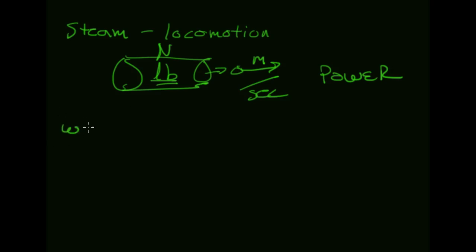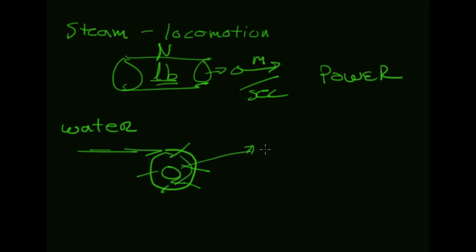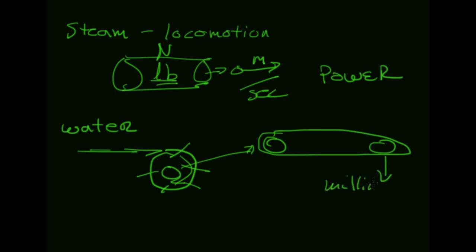We've seen historically that we've used water, and a lot of that is a matter of bringing water over a water wheel. This is like a precursor to the generator idea. So this turns the water wheel, and in turn, that turning mechanism could be geared, with belts and things like this, to turn other things. Using gearing, you can actually perform tasks like milling or drilling or sawing using a water power wheel. No electricity involved, just the water itself is creating the force.